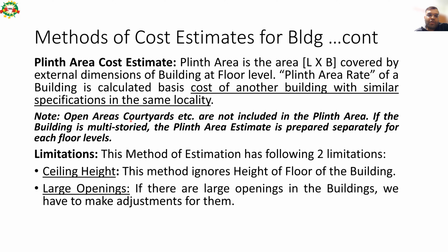Open area, courtyards, etc. are not included in the plinth area. If the building is multi-storied, the plinth area estimate is prepared separately for each floor. So these 2 points we have to note.